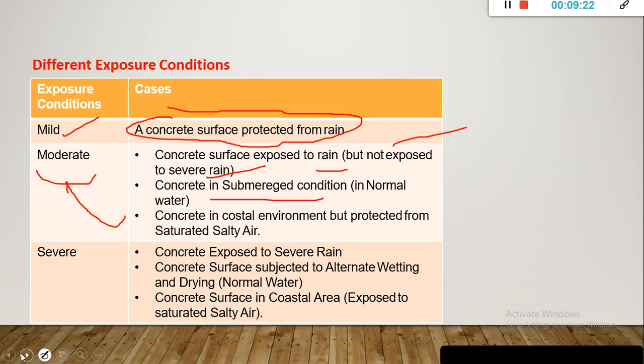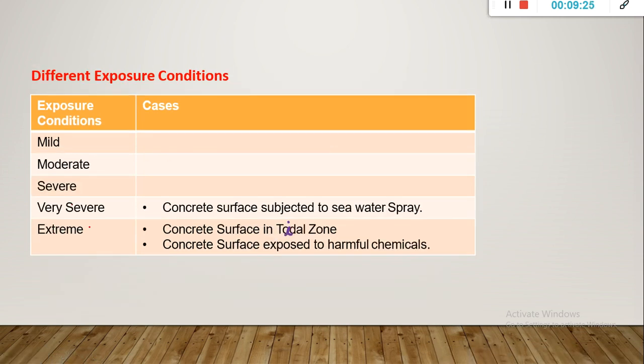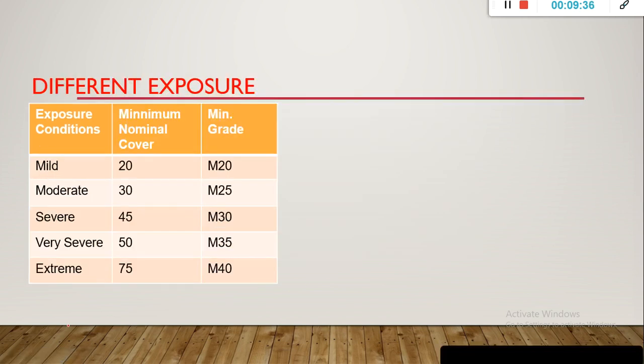After that there are other environmental exposure conditions which are very severe. So concrete surface subjected to sea water spray, and if it is in a tidal zone, then it falls under extreme, concrete surfaces exposed to harmful chemicals. Okay, depending on this, the covers are changed.